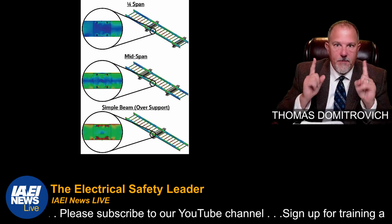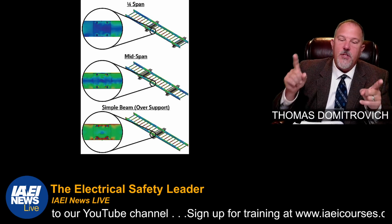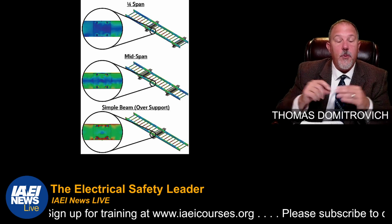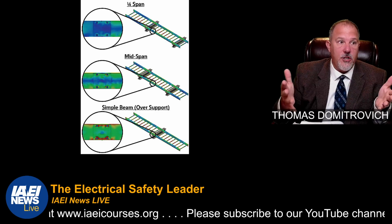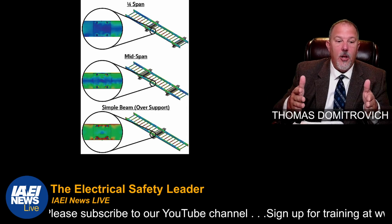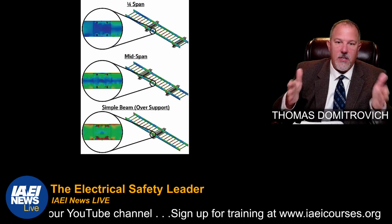The support span, okay, that's the distance of the cable tray between the supports. So now the length must always be longer than or equal to the support span that you have selected for your installation. So where those supports are, obviously you don't want to make it equal. You want to make it longer, or you could do it equal, then you'll be right on the supports as you see there.